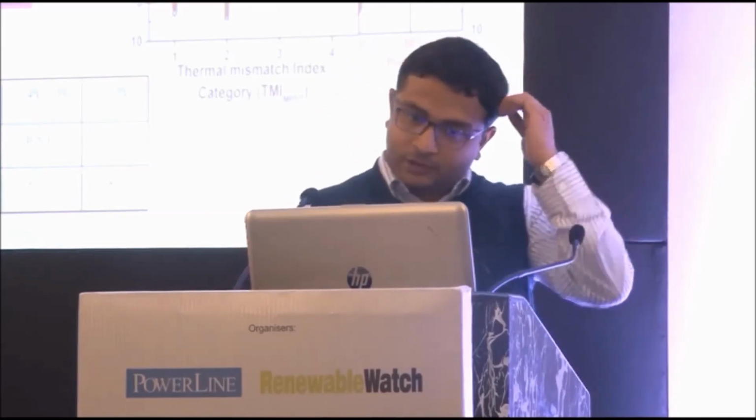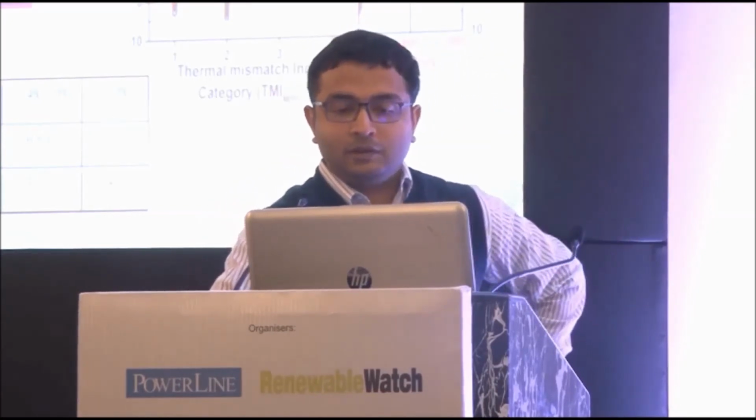Right, so I'll quickly mention the effect of hotspots. What we have found is that through handheld thermography, the hotspots in PV modules do lead to power degradation, and as you can see, when the difference between the hotspot and the module temperature reaches about 4 degrees Celsius, you start seeing significant degradation in power. Below 4 degrees Celsius we have not seen any significant degradation, but after 4 degrees Celsius you do see that.